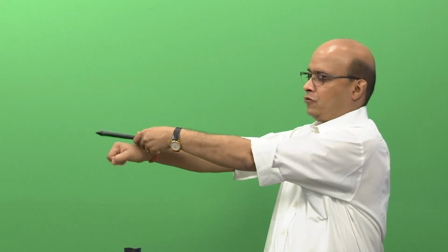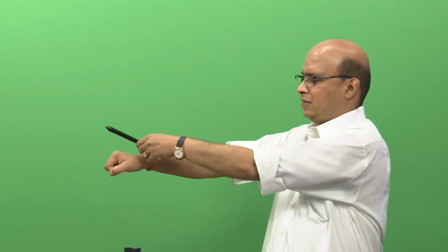So, if you can see the axis here. So, this is my axis, which is pointing outward on this plane. So, this is Z2. Z3 is the elbow axis, which can rotate like this. So, the axis is pointing outward like this. So, this is my Z3. Now, Z4 is the roll axis, which is here for the robot, okay, and Z5, this is the roll. So, and this is the pitch, and this is the yaw, okay, for the robot.